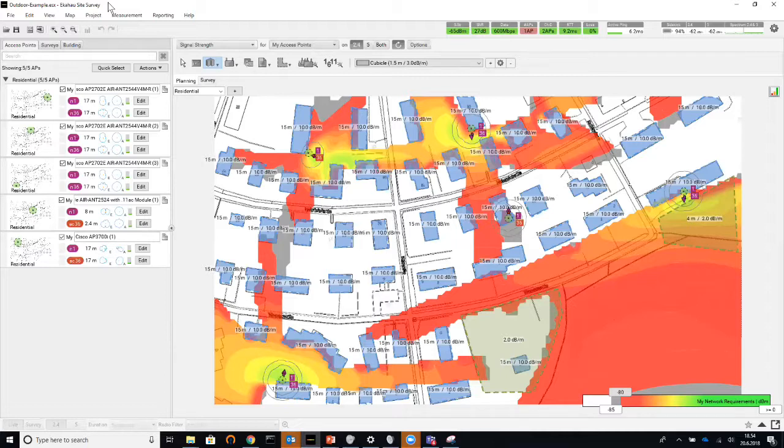You could use directional antennas on the APs, keeping in mind though that if you're also using that band for client access, it's the same set of antennas for both talking to neighboring APs and talking to client devices.